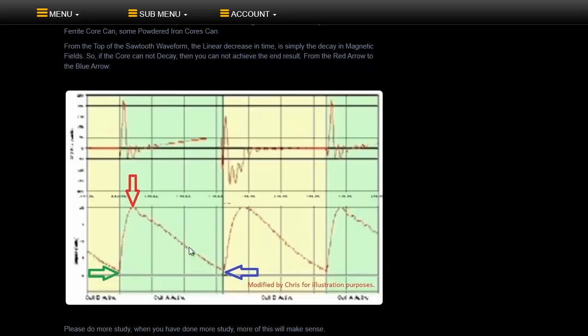This is, I forget exactly, but I think it's 31 kilohertz, which would be a full cycle from there to there, and a 10% duty cycle roughly of input at the start. Each sawtooth waveform is asymmetrical because we're having a difference in the magnetic fields of the coils again.